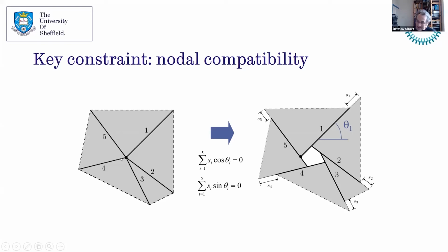What we're dealing with in this case, however, is potential slipline displacements. And the way to visualize that is if you're sitting, for example, just to the left of the node, and you go all the way around the outside of that node and end up back where you started from, then you need to resolve the slipline displacements in the x direction and the y direction, so that each of those sums is equal to 0. And that basically is the key to DLO.